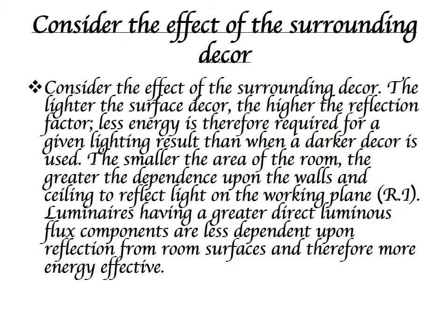Consider the effect of surrounding decor. The lighter the surface decor, the higher the reflection factor. Less energy is therefore required for a given lighting result than when a darker decor is used. The smaller the area of the room, the greater the dependence upon the walls and ceiling to reflect light on the working plane. Luminaires having a greater direct luminous flux component are less dependent upon reflection from room surfaces and therefore more energy effective.